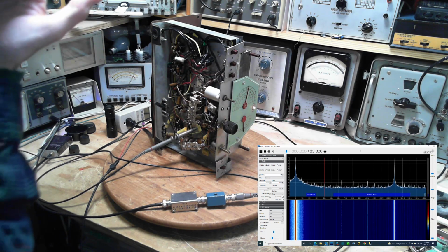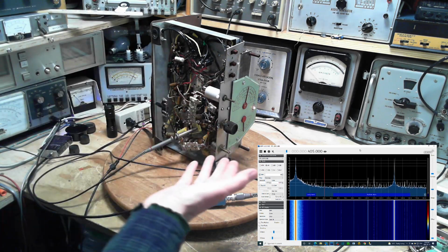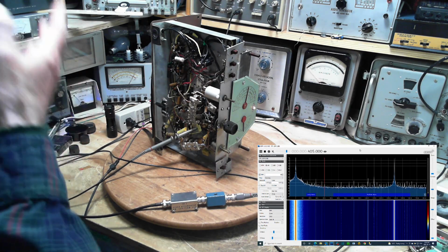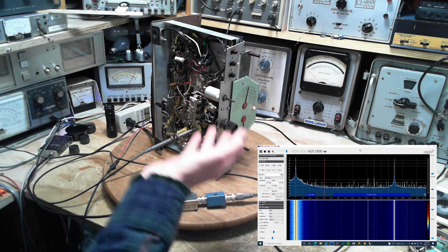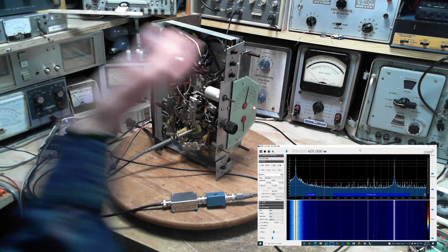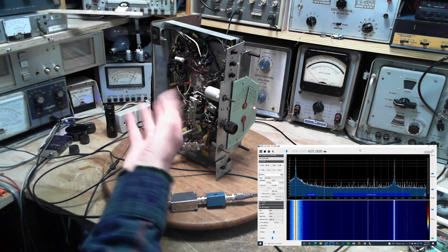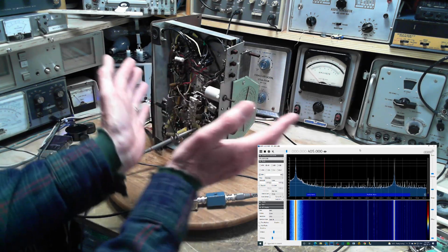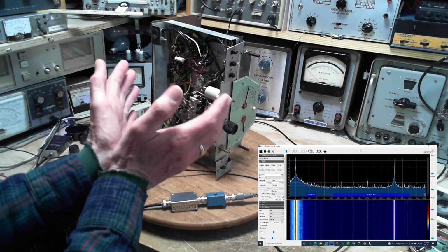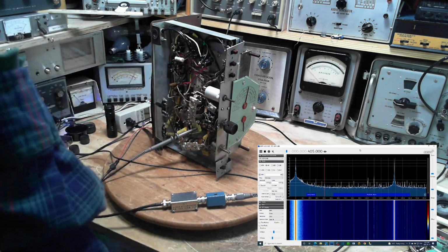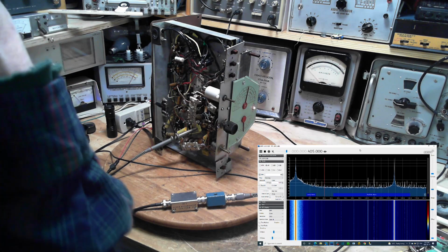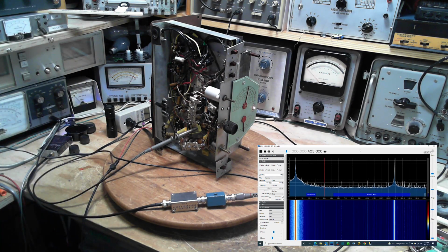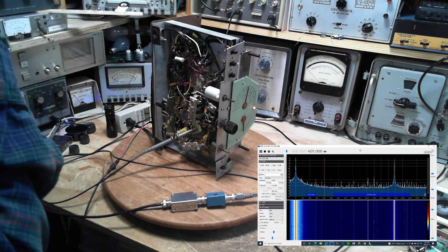Of course, the reason I'm doing it with this radio is because this one has no front end RF section. The antenna basically goes straight to, not quite straight, but through a slightly crooked path to the grid of the first tube, the mixer tube. So this one's got a wide open mouth on it, and everything that's on that antenna is ending up more or less on the grid. Now it's suppressed. It's suppressed by antenna tuning.